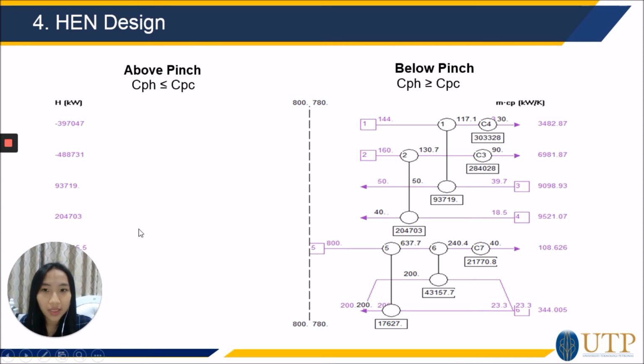For our case, this is the final hand design. There are 7 heat exchangers in total, and that is because we cannot perform loop breaking and path. When we perform loop breaking, a temperature violation is present, and the only way to solve the loop issue is by carrying out path. By carrying out path, we actually need a heater, because path literally means the connection of heater to cooler. So the temperature violation is not feasible. So we just stick to this as the final hand design.